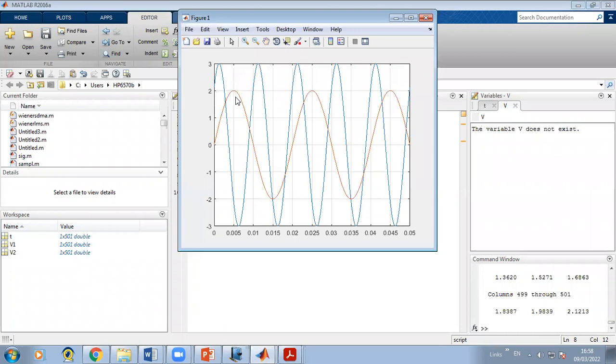Now you can see we have two signals, no? This is our second signal, the high amplitude signal, and you can see it is 100 hertz. That means this other one is 50 hertz. So the blue line frequency is much higher, actually twice this one. For the composite signal, this value and this value should be added, and we get one value. We have to add all these points from this signal and this signal.